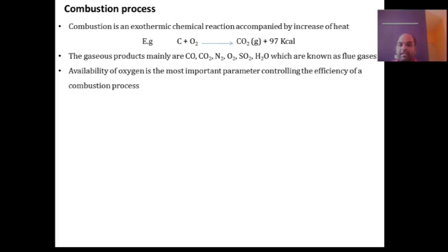And also the heat that is liberated is much lesser, the temperature that you achieve is much lesser, and that is why an incomplete combustion results in a yellow color flame. On the contrary, when you have complete combustion, for example, what happens in your gas stove, you'll see a blue flame, and a blue flame indicates a higher temperature which is reached because of complete combustion, which means that enough oxygen is actually supplied to the burner.